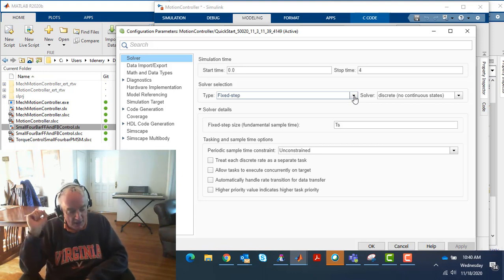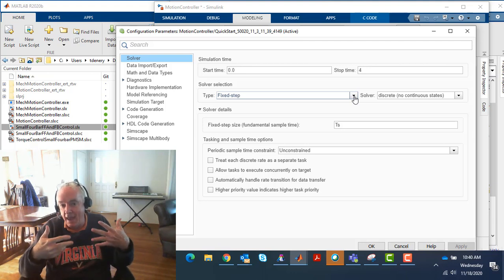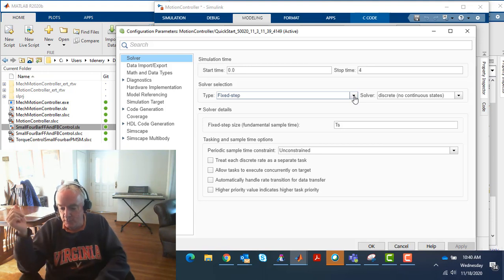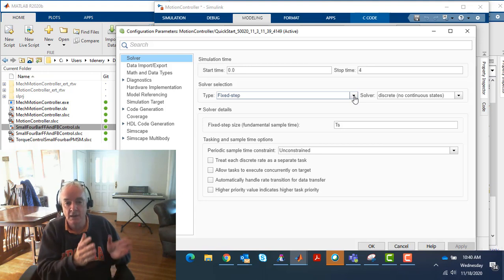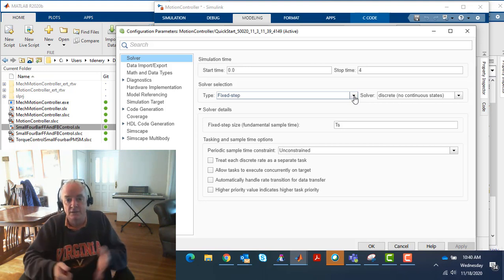And these methods are very good at understanding if it's numerically converged based on some accuracy settings that you may have chosen. But anyways, if it does not, the idea is go back and try again with a smaller delta t, and continue reducing the delta t until you get an update of your system that does satisfy your accuracy requirements.